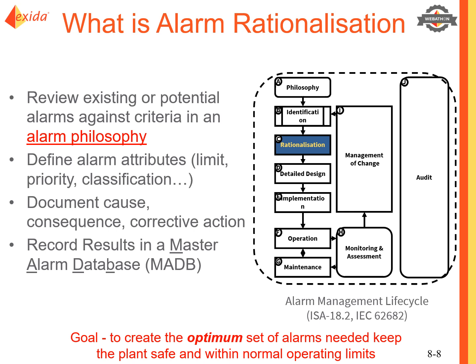Does it require a timely response? So once we've defined that it is an alarm, we can then look at the alarm attributes, its priority, its classification, and we can document all that. We can document the cause, the corrective action, the consequence, and we record them all in our master alarm database.